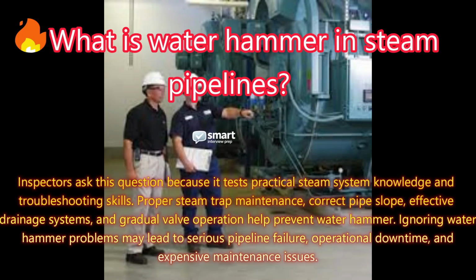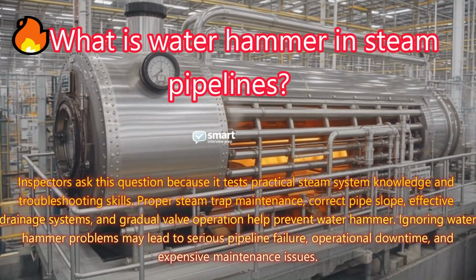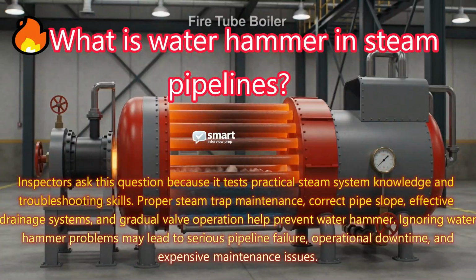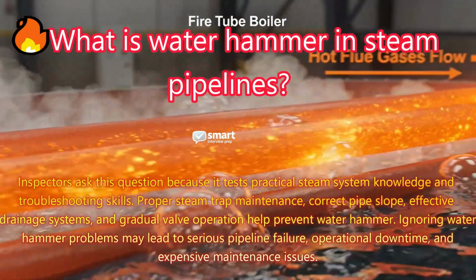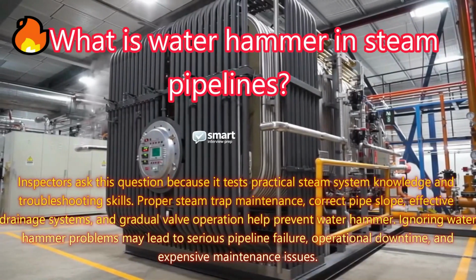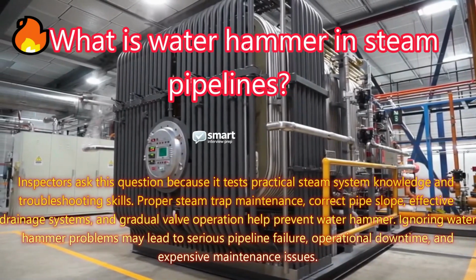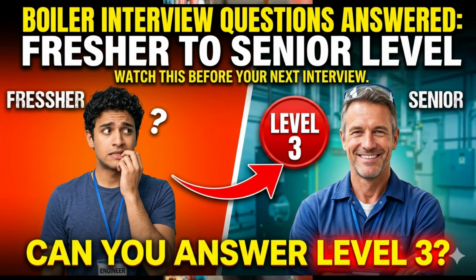Inspectors ask this question because it tests practical steam system knowledge and troubleshooting skills. Proper steam trap maintenance, correct pipe slope, effective drainage systems, and gradual valve operation help prevent water hammer. Ignoring water hammer problems may lead to serious pipeline failure, operational downtime, and expensive maintenance issues.